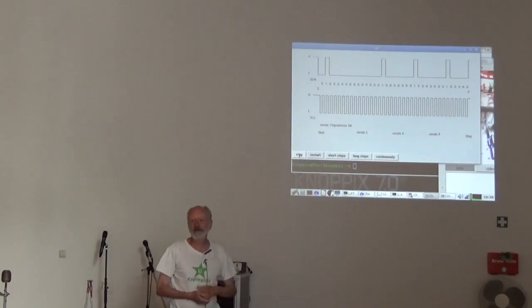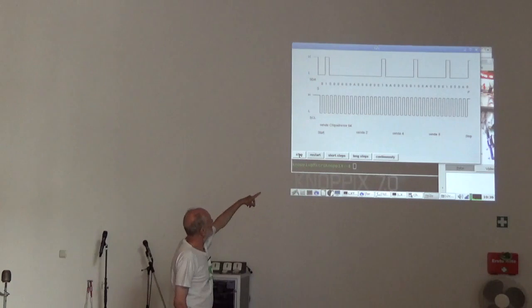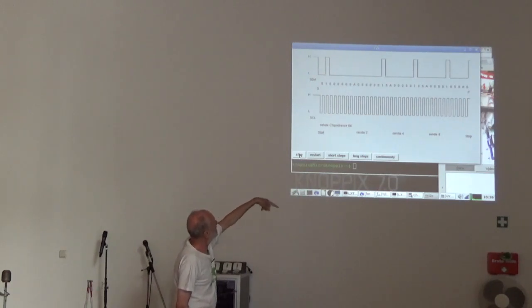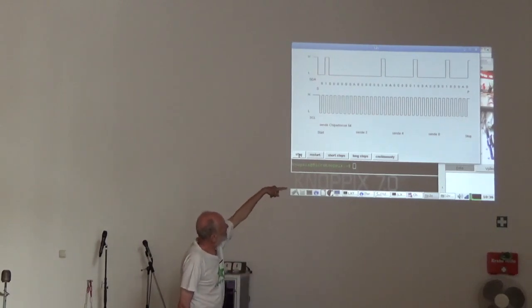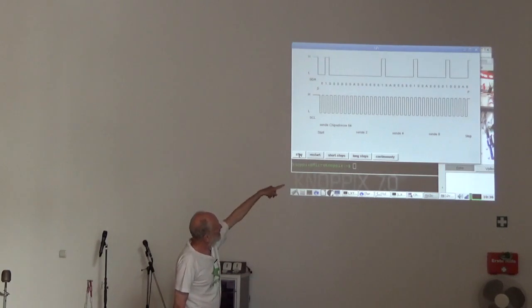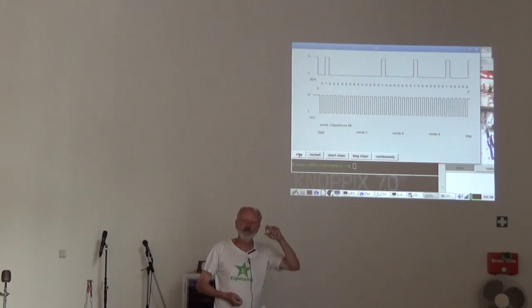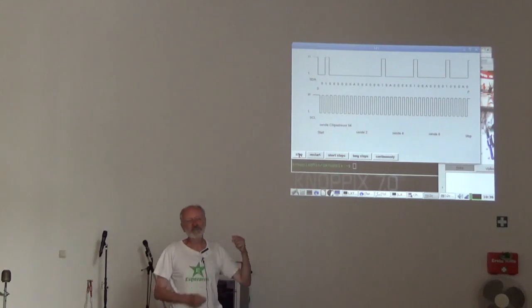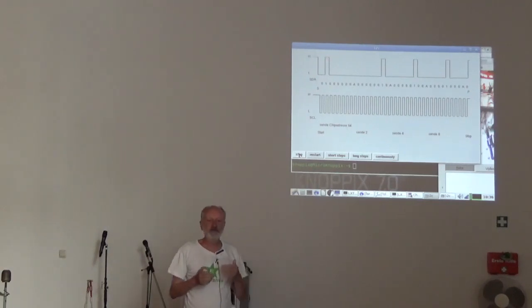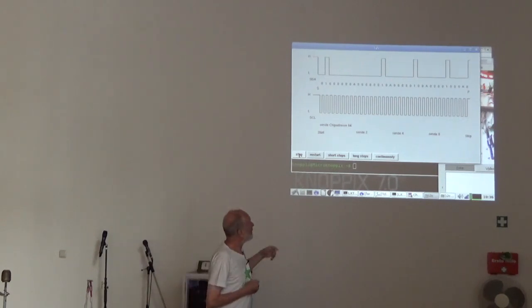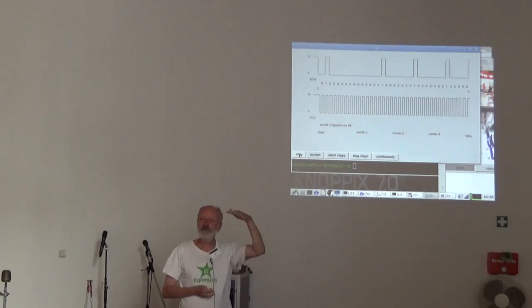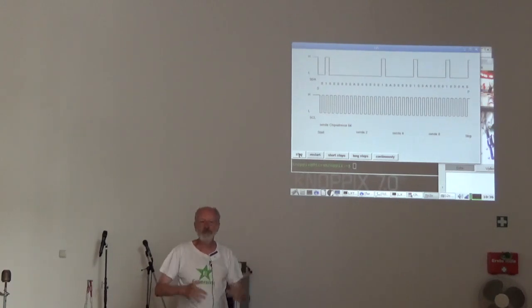Next, I send the data. I send a 2, I send a 4, I send an 8, and every time I send it, you maybe observed that an LED was switched off. So in this demonstration, when the data has a high bit, then the LED will be pulled down and it's off. And when I send a low bit, then it is on.